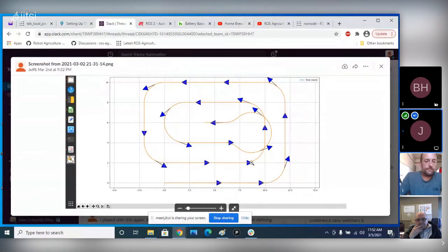So see, each time I go on the thing, this part of the vertical line gets shorter until I get down to the very end. And this one, you see, creates one exact arc. The smaller you get, it gets down to the point where instead of putting an arc and a line and an arc, it now just draws one big arc, because that's exactly a 4-meter diameter turn. And then you come down to the end here, and I said, well, I want to go to a row 2 meters away. It can't do that, so the Dubins path generates the light bulb curve to make that turn.